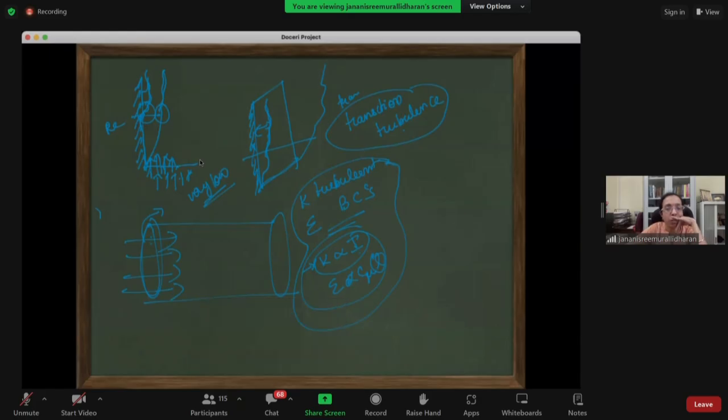Okay, so someone is asking: for different geometries, how will someone know the critical Rayleigh number, so that I can decide which model can be used to reduce the computational cost? I think this is again a very trial and error process, because for each geometry it is going to be different. It's just trying to understand what your Grashof number is coming out to be, and your Reynolds number.